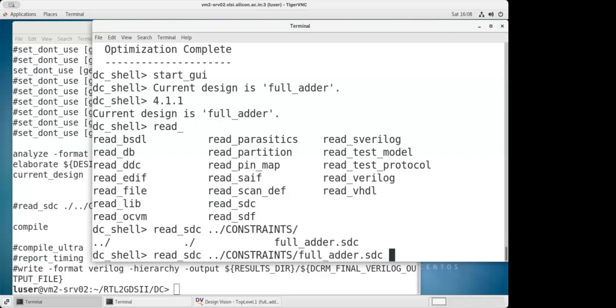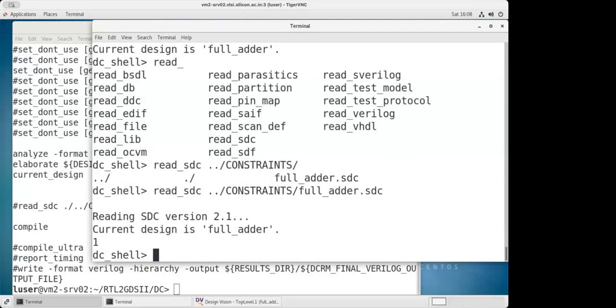The AO cell is a big cell, giving me a lot of delay. So the tool figured out from the library which other cell it can use in place of this, which can give less delay. And that's the reason everything has changed.